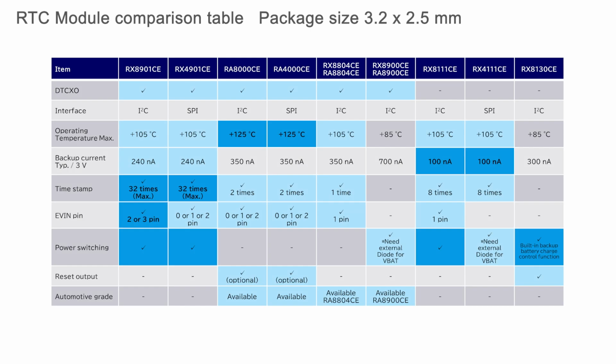Epson offers an extensive lineup of RTC modules with a built-in 32.768 kHz crystal unit. These products do not simply keep time, but also include products that maintain accurate time even in high-temperature environments and products with various functions. This list is a comparison of the functions supported by RTC module products in a 3.2 by 2.5 mm package size. All RTC module products support the basic RTC functions of time, calendar, alarm, and wake-up timer. The areas shaded in dark blue indicate recommended products for each function.